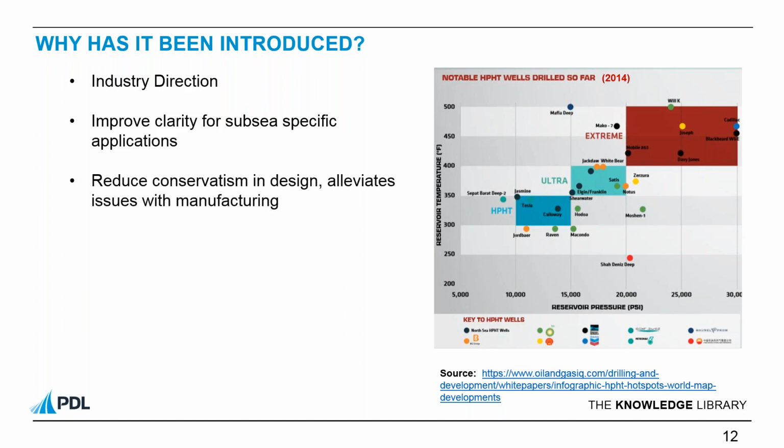Thirdly, there are a number of manufacturing and installation issues which become more problematic as the equipment becomes bigger and heavier. For example, mechanical handling becomes more difficult, and ensuring adequate and consistent through-wall material strength properties becomes more difficult. It's intended that by utilising more advanced analytical tools and adhering to stricter product specification levels, some of the design margins can be tightened, leading to more efficient designs which alleviate some of these issues.